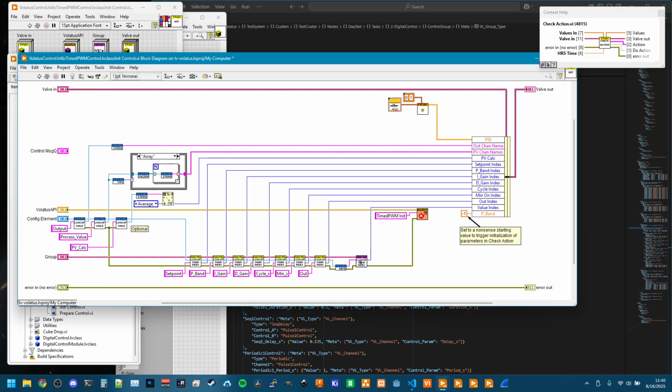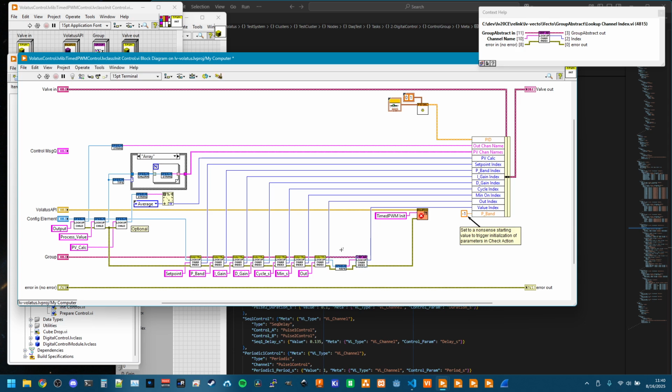Under the hood, these groups of data are implemented as by reference with a data value reference. And so anytime we needed to get data in and out of those, it needs to spend just a little bit of time unlocking that reference and gaining access to that. And that could get slowed down if anything else is reading data from that group, or if like the scaling and data processing and logging part of the code is modifying values in that group.